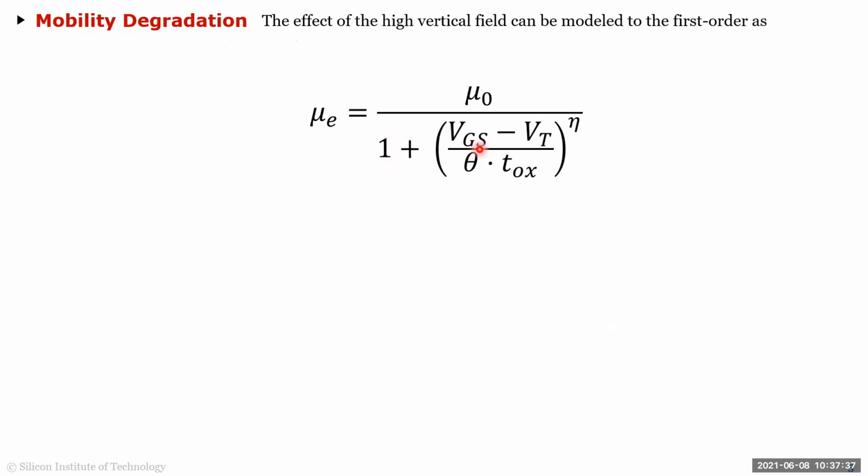Okay, so I'll just quickly show you again. This is what is derived in your Hodges book, the reference textbook we have been using. This is an empirical formula for people to use for hand calculation. But if you look at the model, it's a lot more complicated. I'll show you the BSIM4 model at the end of this lecture. I'll open up the manual and show you how complex each of the equations is. That's why, instead of 5 parameters, you have 100 parameters, like in BSIM3, and in BSIM4 it's even more.